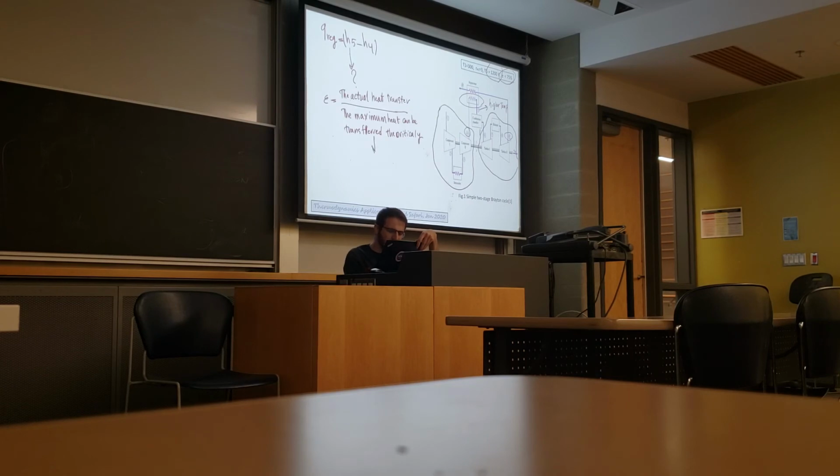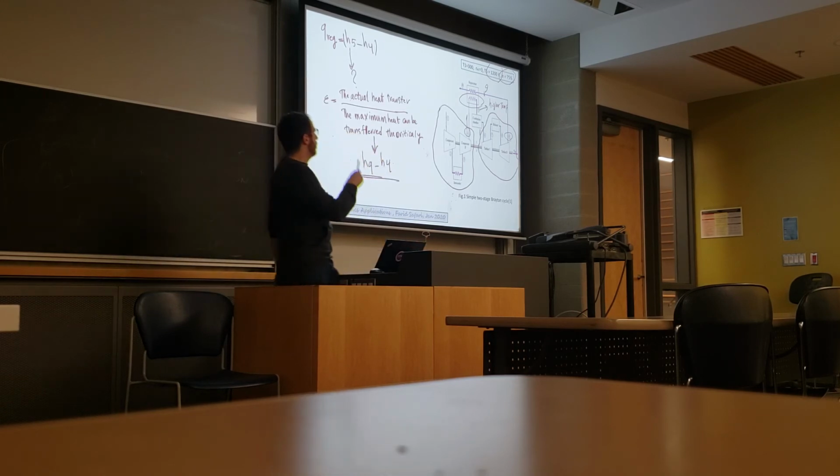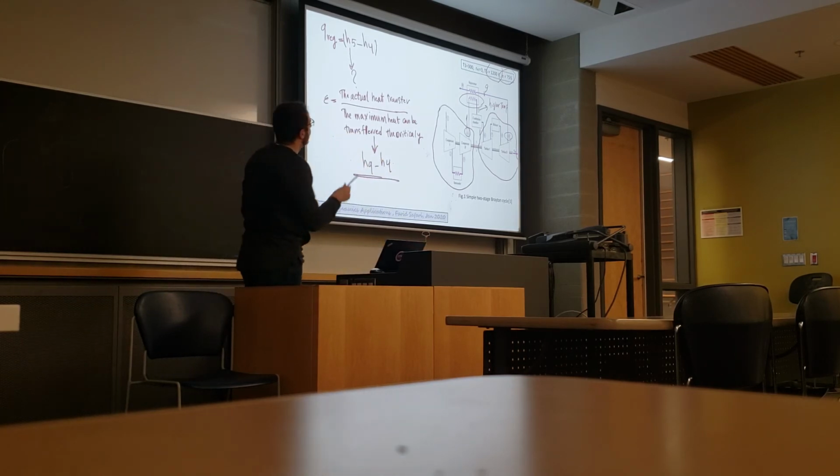So what is the maximum heat that can be transferred theoretically here? We have a hot flow of 9. We want to gain some energy from the flow of 9 and give it to 4. 4 is the coldest stream, 9 is the hottest stream. So basically the difference between 9 and 4 is the maximum that theoretically can be gained, meaning H9 minus H4.